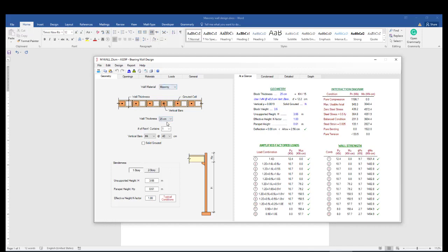The first thing is we want the thickness. We have 20 and 25. That 25 is okay, and there are two options. We can use two rebars, which I already showed in the pictures, or you can use a single. The single is enough. We can use D10 at 20 each, one here, one here.